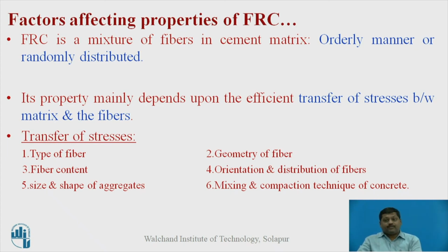Now what are the sub-factors which will affect the transfer of stresses? First is type of fiber. Second, geometry of fiber, whether it is a plain fiber, crimped fiber or hooked fiber. At the ends, what is the geometry, that is also important. Third is fiber content. So percentage of the fiber is important. Fourth is orientation and distribution of the fibers. If it is distributed properly, if the fiber orientation is perpendicular to the crack, definitely that will arrest the crack more effectively.